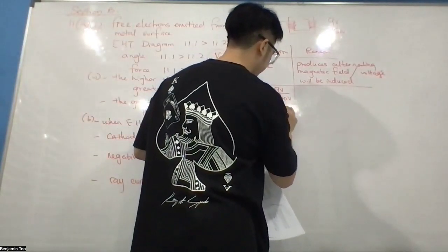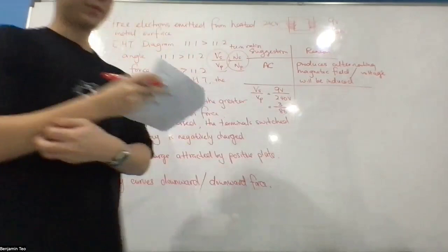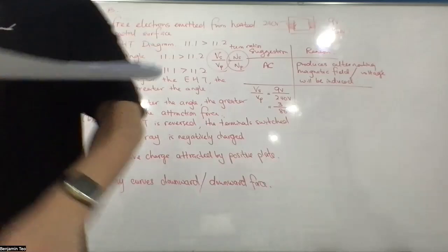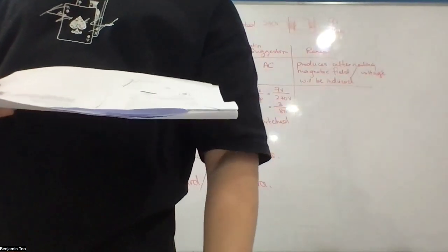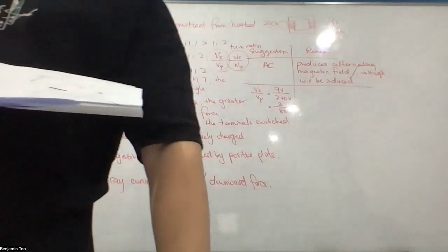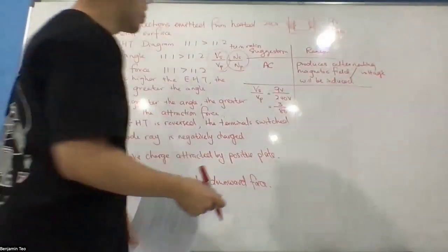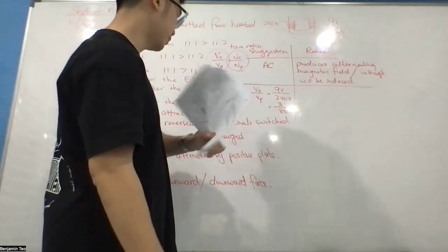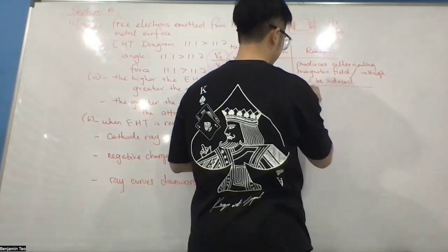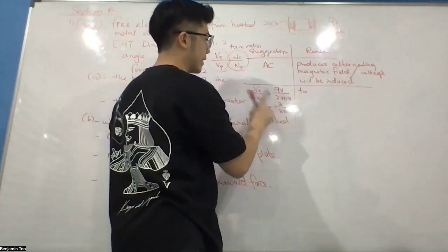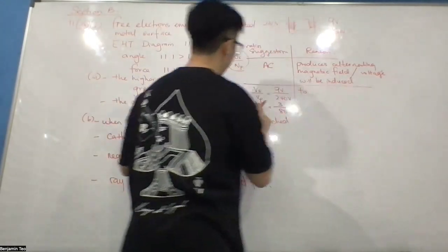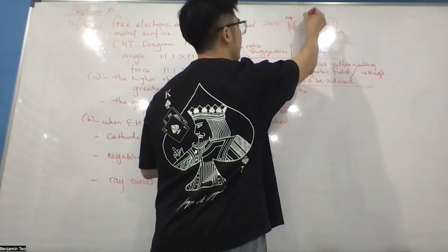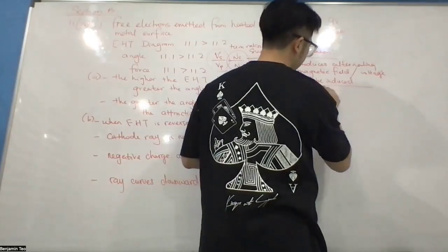Over 80. Okay, and the reason why you want to use 3 over 80: this is a step down transformer. So you say to reduce the output voltage, your turn ratio is less than 1, meaning that here is higher turn, here is lower turn. So to reduce